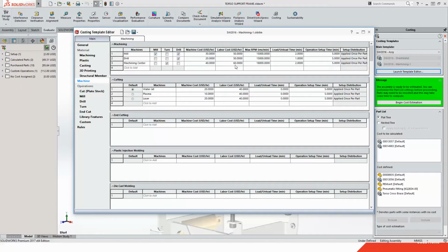There's an interesting detail that we also apply to this, and it has to do with setup costs, and whether they apply to a single part or whether they're divided over the total quantity or total lot size. When you can set up a machine once and then amortize that cost over a series of components, of course the cost per part will drop as a result. So we want to be very specific when it comes to these types of details.